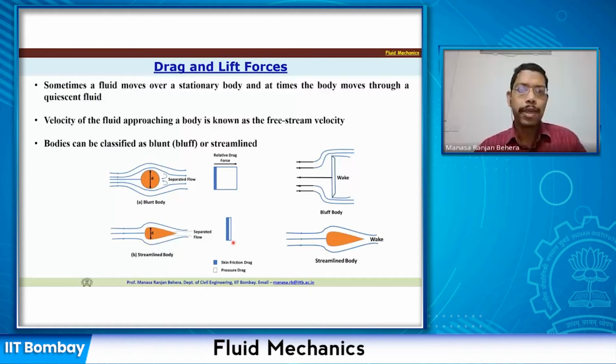So let us see, you have this body which is a cylinder or a sphere. Okay, whatever you take. So what happens, the flow is going to deviate and then it will rejoin, but there will be some kind of wake formation or low pressure region which will be formed on this side. And why it is going to happen, we have already seen in our previous lecture that there is a possibility of flow separation. Okay, so because of that, there could be a low pressure region on this lee side, and that could lead to the pressure drag, and that pressure drag is going to be substantially higher compared to the skin friction drag. Okay, so these wake regions contribute a lot, and the magnitude of the pressure drag is going to be much higher compared to the skin friction drag.